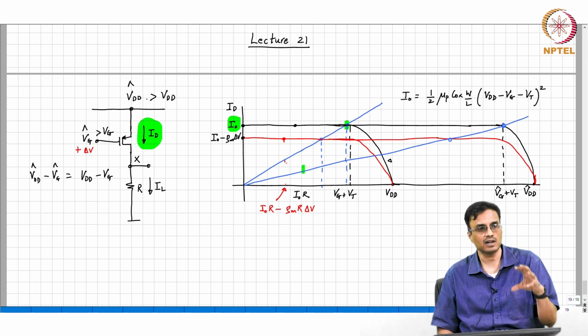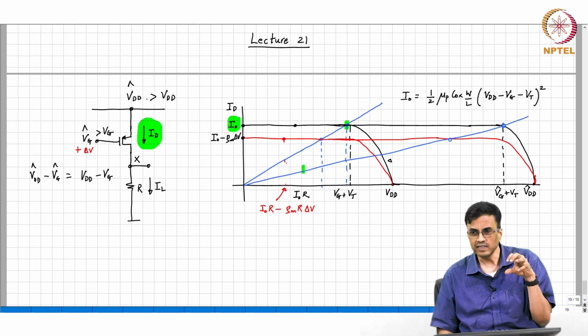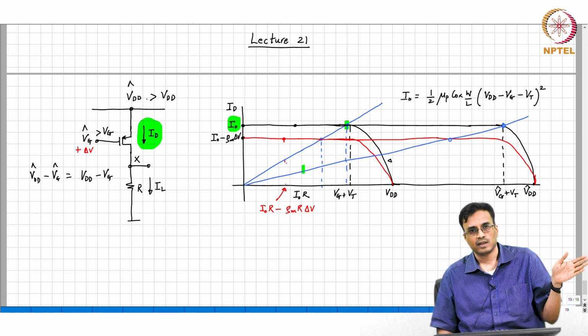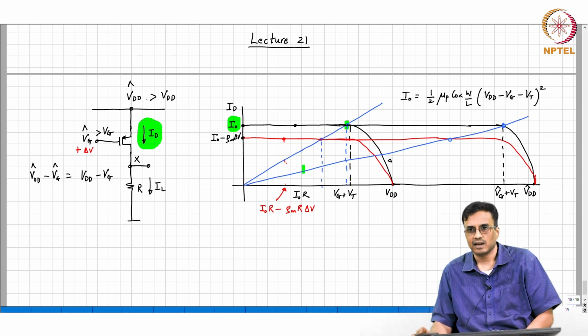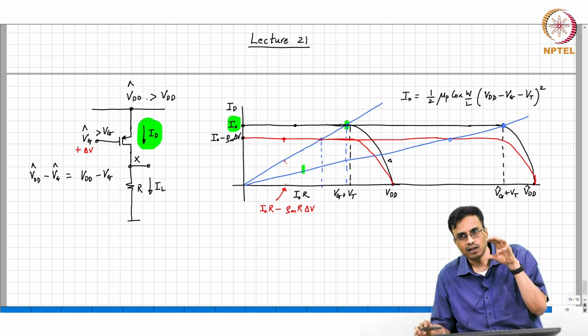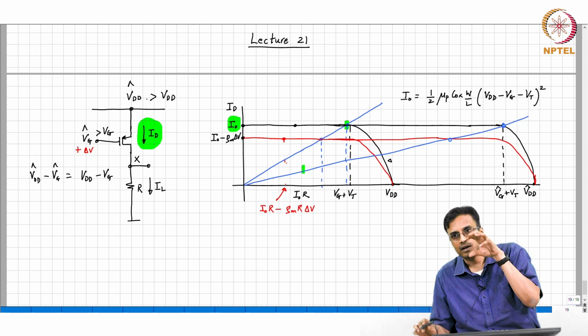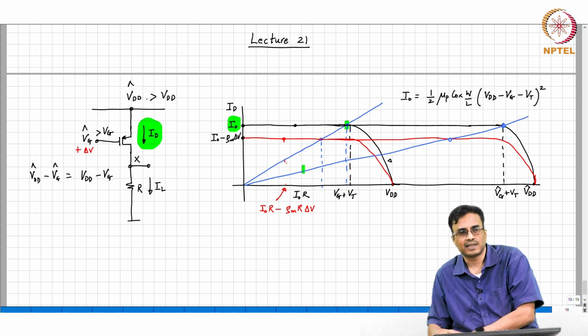So, with this transistor having this gm, the only way of getting a larger incremental gain with a resistive load is to increase the supply voltage and increase the gate voltage by the same amount, so that the transistor still carries the same current, but you increase the resistance, so that even with the increased VDD, you are operating at the edge of the saturation region.